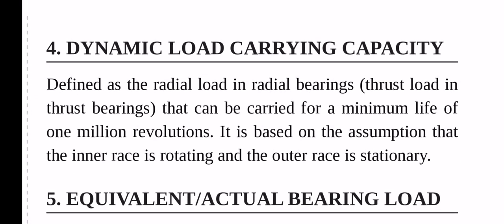Dynamic load carrying capacity is defined as the radial load in radial bearing, or thrust load in thrust bearing, that can be carried for a minimum life of 1 million revolutions. It is based on the assumptions that the inner race is rotating and the outer race is stationary.